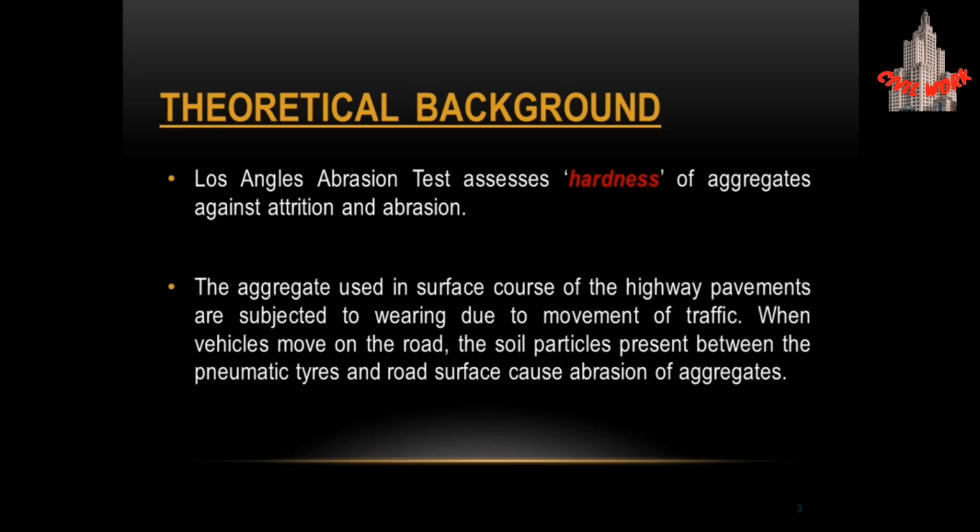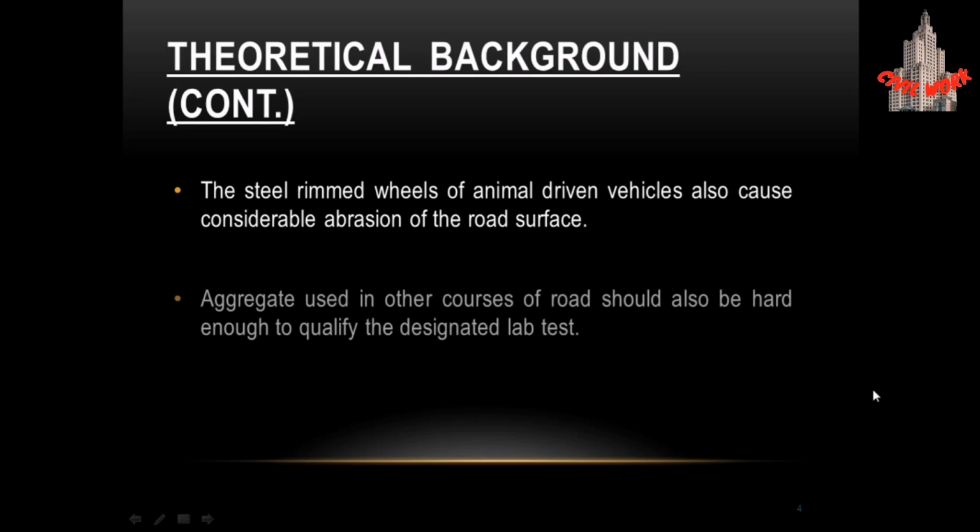Los Angeles test assesses hardness of aggregates against attrition and abrasion. We have discussed these both terms. The aggregate used in surface course of the highway pavements are subjected to wearing due to movement of traffic. When vehicles move on the road, the soil particles present between the pneumatic tires and road surface cause abrasion of aggregates.